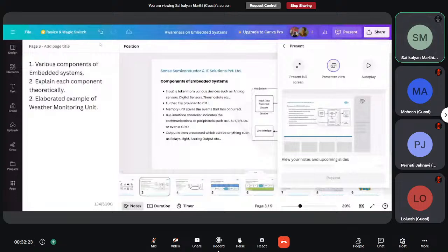We have different sensors which need to be integrated. So the software team will get: you have one sensor communicating over I2C, one sensor communicating with the UART, and one sensor communicating with the SPI, and those data sheets will be given to the software team. Then the software team will analyze the resources, identify the resources which the controller has, and then they do the